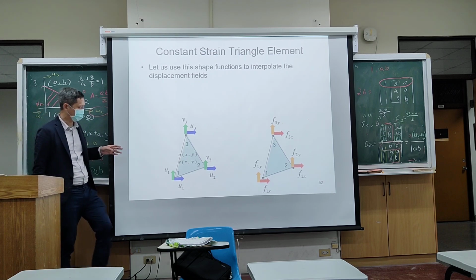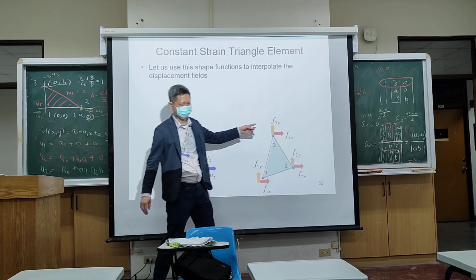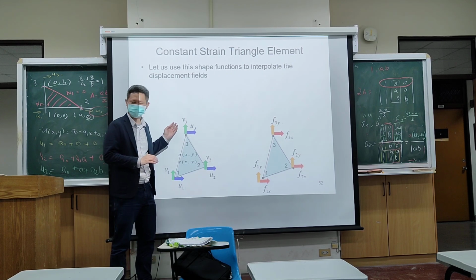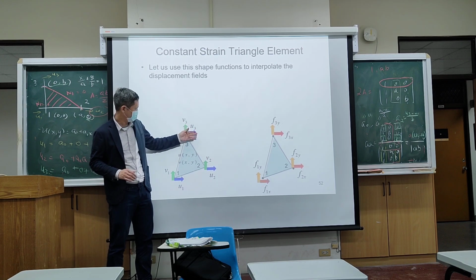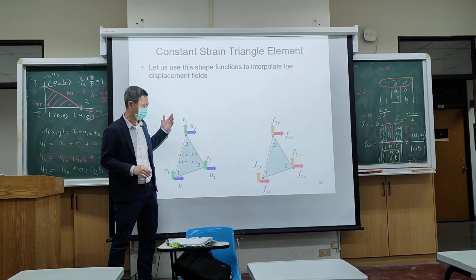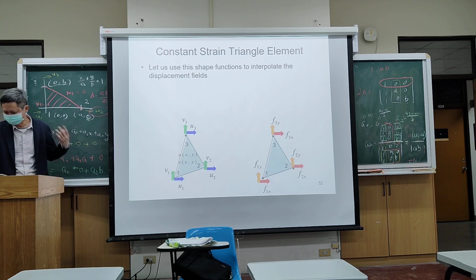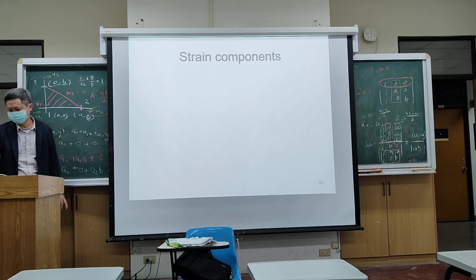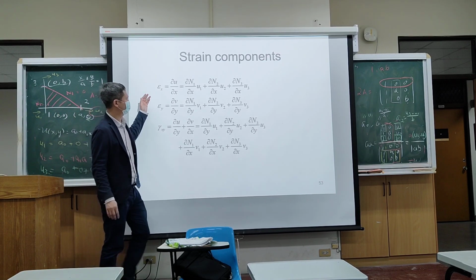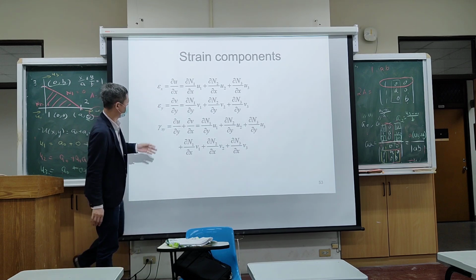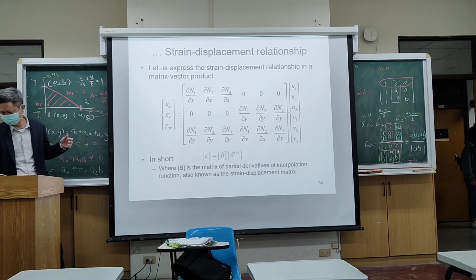So now what we're going to do, we're going to relate displacement to the force. We have spent a lot of effort interpolating the displacement in the x and y directions. And we also obtain the constant strain. So now, how are we going to relate it to the nodal force? To relate it to nodal force, we start by applying these strain components and their relationship to displacement.